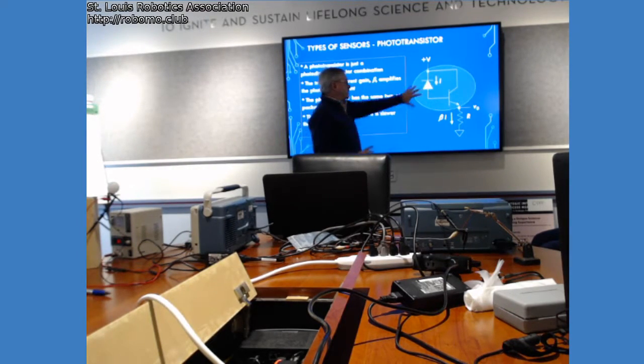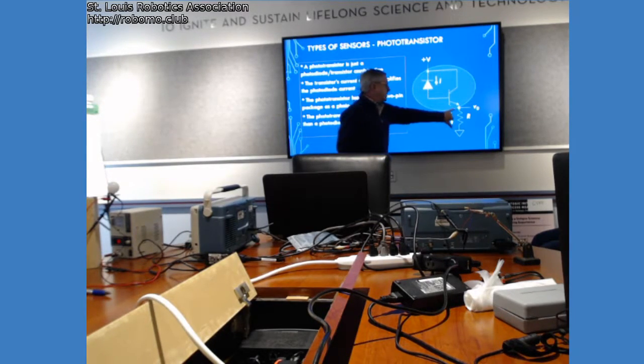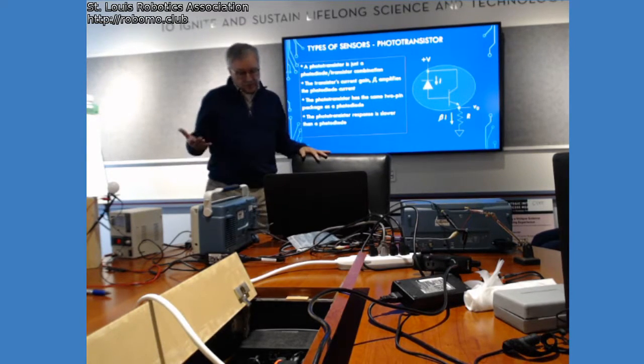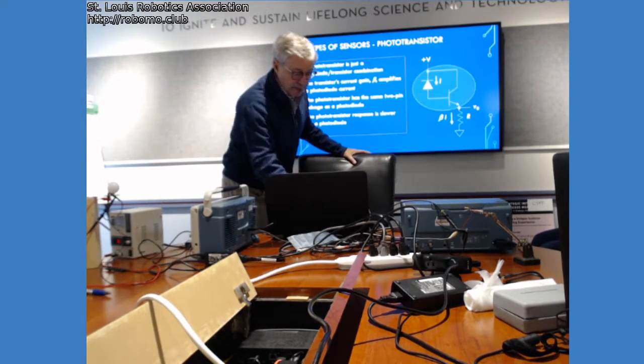So the bad news is it's slower by maybe a factor of beta. The good news is it's got more current by a factor of beta. So again, it depends on your application. What are you looking for?